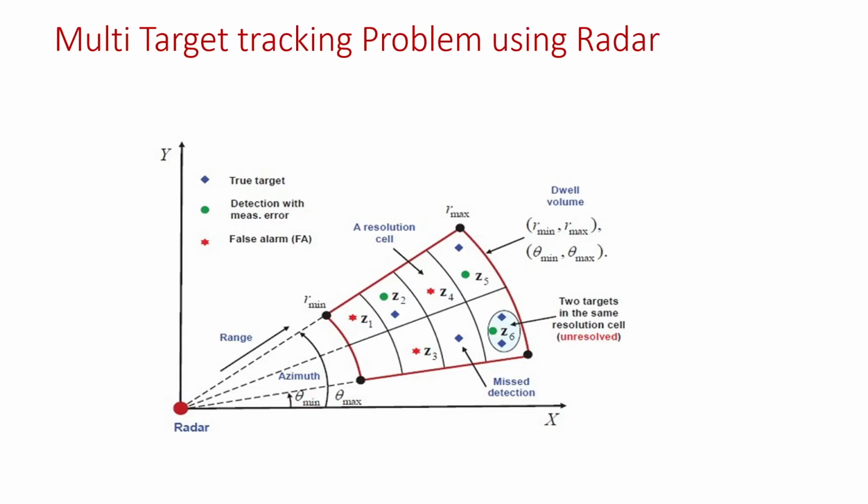So, this is a problem of a typical bistatic radar, using that how the actual radar measurements are happening. If you see, these are all called radar resolution cells. Okay. Greens are actual measurements. Blue, this kind of a rhombus, are actually two targets. So, blue are two targets, green is measurement. The two targets are very closely spaced to each other, within one resolution cell. Radar won't be able to identify that they are different targets. You won't identify the two, it will give only one measurement.